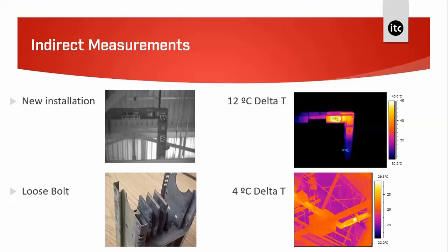The heating source may be some distance away, which it is, and for this reason, it's difficult to estimate the internal temperature accurately. Added to this problem is the fact that a lot of these have a low emissivity finish on the exterior, which means they could be reflective. Some knowledge of the construction and assembly can be of benefit. It can give us an indication of where the joints are. So local heating near a joint could be viewed as a possible indication of a problem with the joint, and the temperature inside may be really high, even though the external temperature rise may be low.